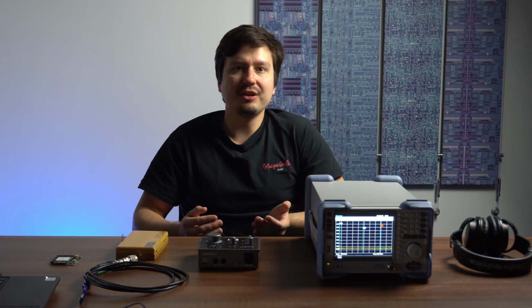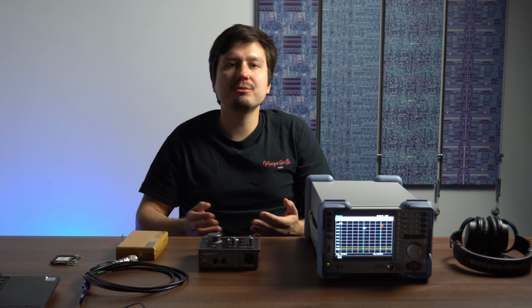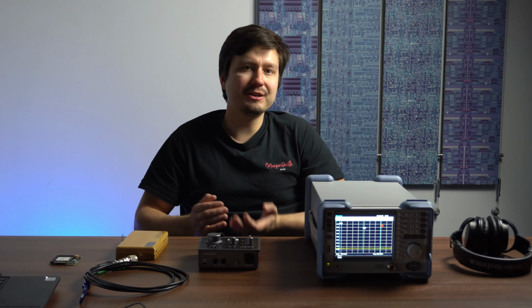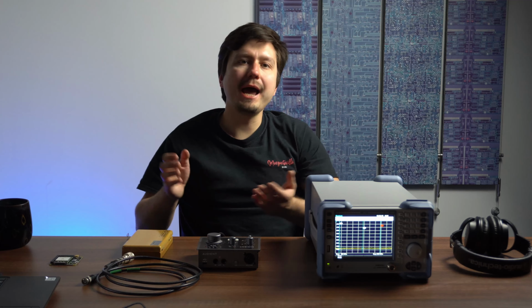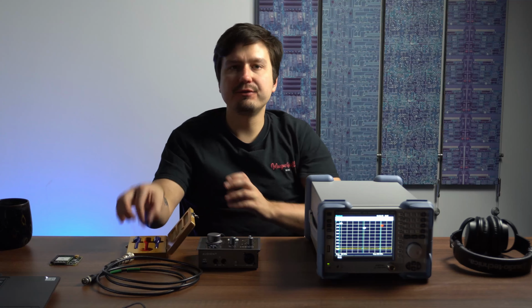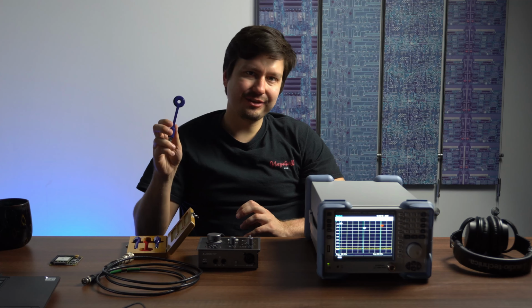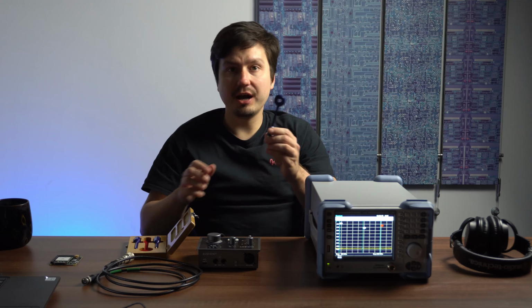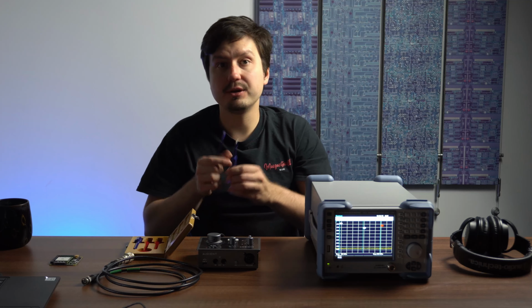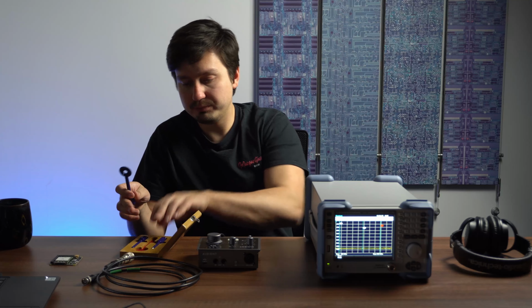Instead, I'm sitting in an average office environment, so it's not going to be possible for me to accurately measure the performance of my device in a far field. So what I'm going to do instead is use my near field probes and measure the performance of my device in a near field. And to do that, I have a choice of electric field and magnetic field near probes. So I have 3 near field probes here.